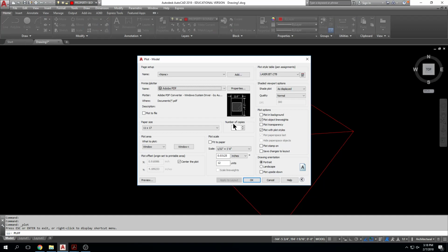Now, again, my methodology for LT scale is that I set it to half the scale factor. If that doesn't work, then I do half that number. And if that doesn't work, I do half the number again and half again until it works, okay? LT scale isn't something that is going to mess anything up, right? I said this last time. It's just a view setting essentially in AutoCAD. It doesn't scale the scaled object. It doesn't mess anything up. So you can change it 50 different times and nothing is being affected really in AutoCAD, okay?